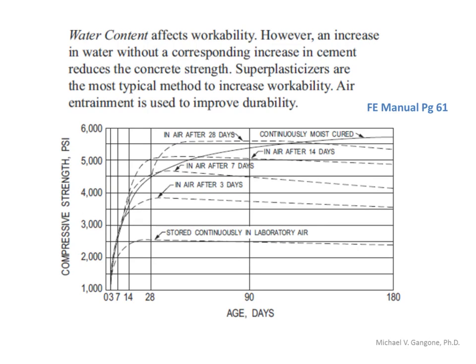But curing method is also something I want to point out here that's very important, and it's very important to make sure that you cure the concrete appropriately. When we're curing concrete, we're allowing the concrete to fully hydrate. That's the important thing to keep in mind. By doing that, we're controlling the temperature and the humidity level of the concrete to keep the moisture in and allow the hydration to fully occur.